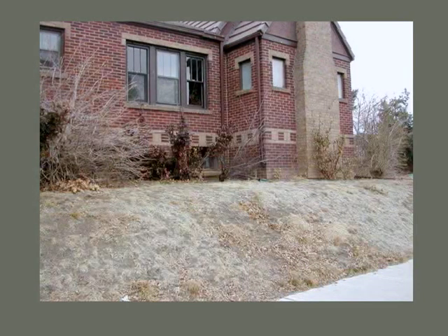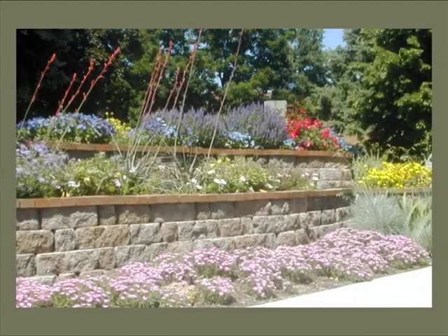Here is an ugly slope, and here is the wall that was built. Now this is a concrete block wall, and this does have interlocking loops. I did go through this phase when I was obsessed with interlocking loops. By building in concrete block, it's a gravity wall, it's completely engineered. So engineers at the places that produce these products determine exact standards for how to make this wall fit together. It's like Legos, and how high it can go and what needs to go behind it.